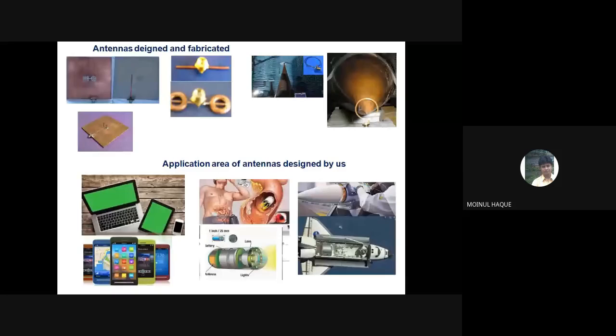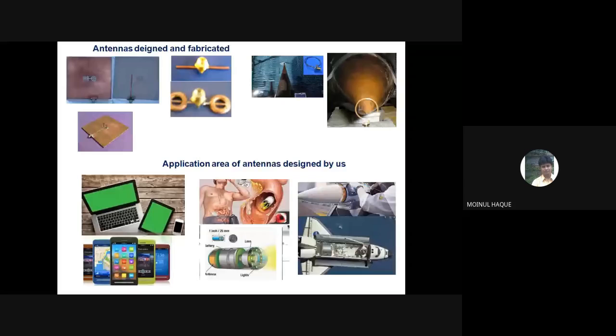Okay, so efficiency should be 80%, 90% in that range. So that is why the antenna which we have designed does not use any spiral kind of structure. You see here a simple dipole antenna, loaded with only two loops instead of a coil or spiral structure. We have used only a single loop.